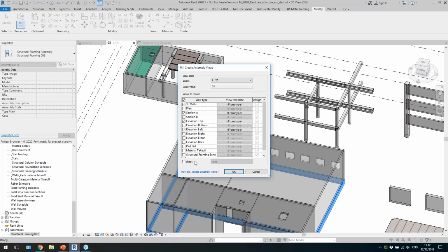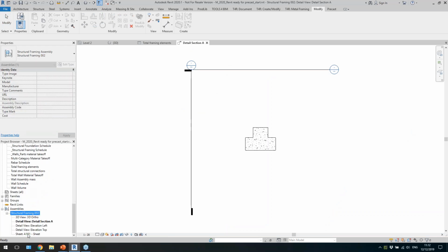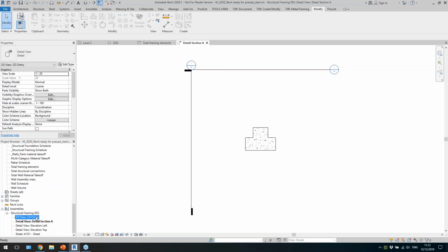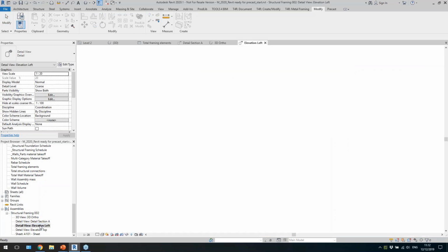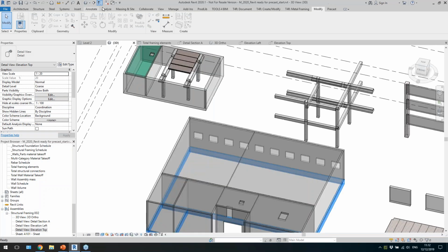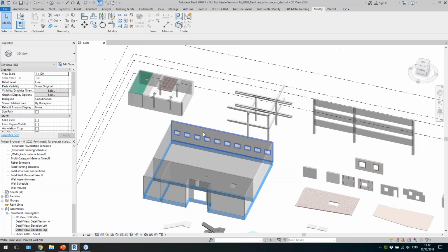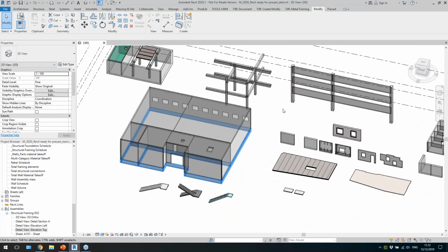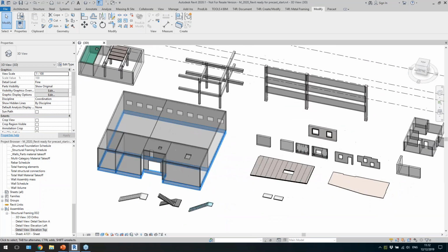So for example, I select a couple of views, the sheet which should be here, and then I get these separate views of a separate element. You see, it's only this beam, and then I can go on and tweak it to make it a shop ticket or something. But that would be one of the ways, right, how to work in Revit.